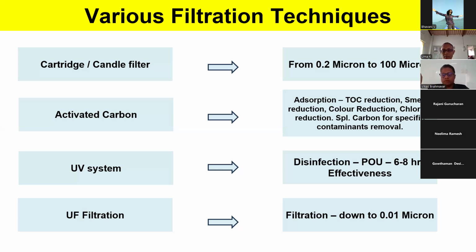So that is a point of use. As I said, 6 to 8 hours is the effectiveness. So if you have a UV before your overhead tank, generally it's not effective because you end up storing the water. There is water at the bottom, so it's not effective. It should be after the storage tank. If you have UV there, it is effective.